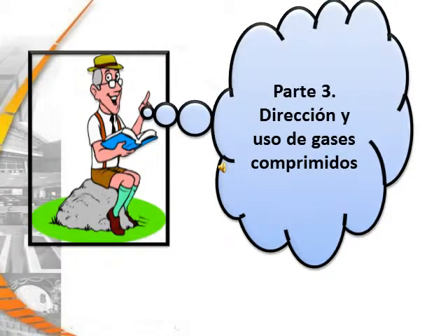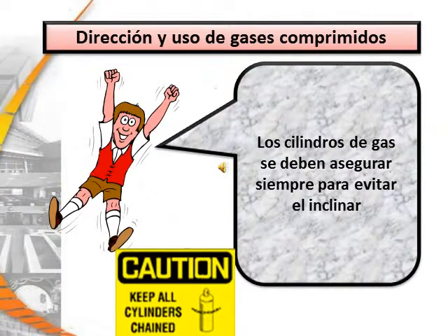Part 3, the handling and use of compressed gases. Gas cylinders must be secured at all times to prevent tipping. Keeping cylinders capped is another way of preventing the hazards from getting out of control.